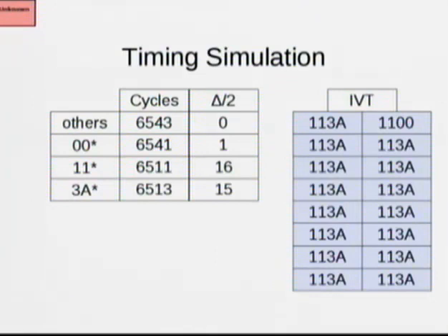You'll also note that this password isn't very random. It wouldn't take you terribly long to guess this if you knew the general pattern. And the pattern is that every one of these words is an address in memory at which executable code exists. This is the interrupt table. When the machine turns on, it looks here at this word, and that's where it begins execution. All of the unused vectors have the same word in them.